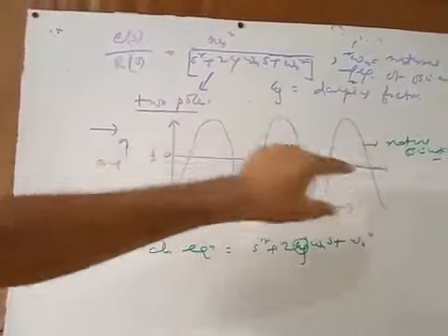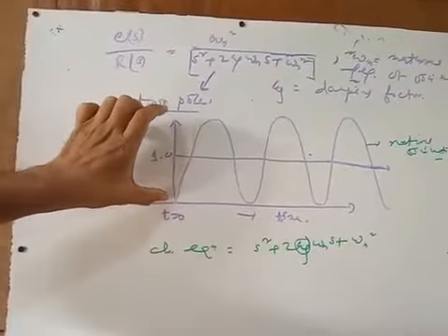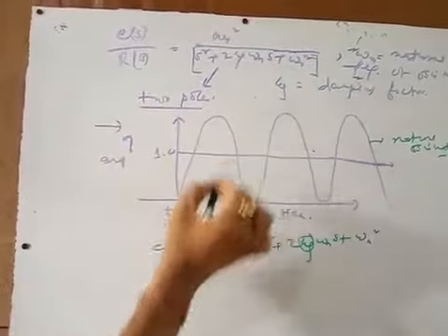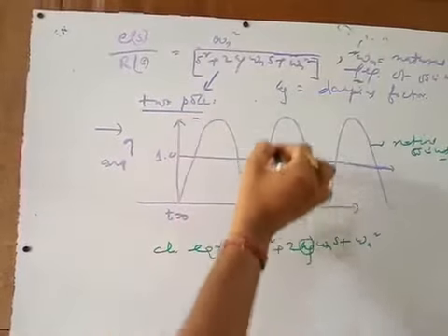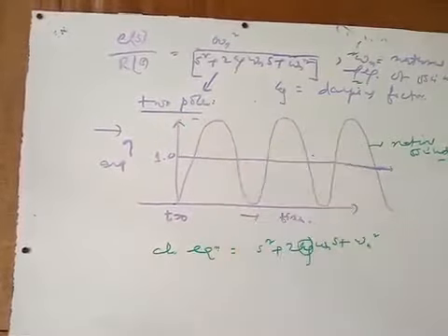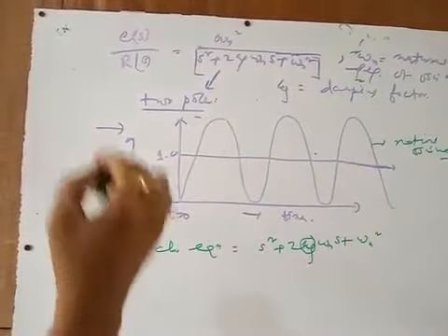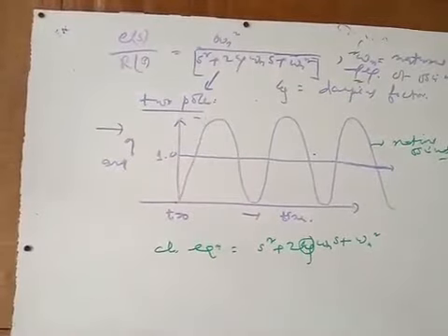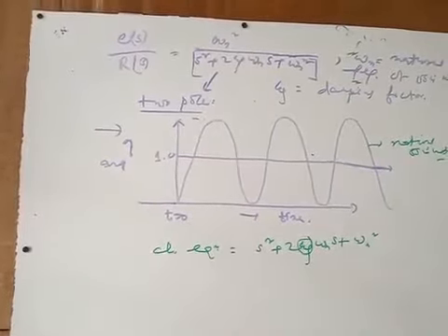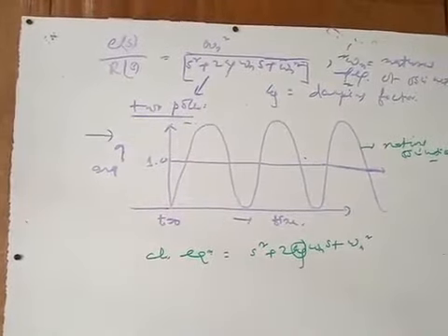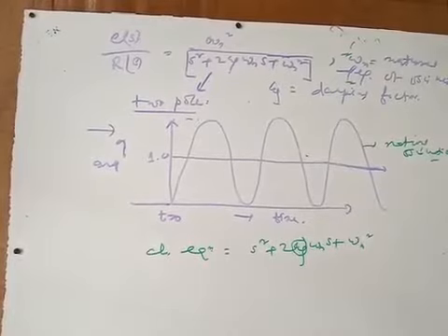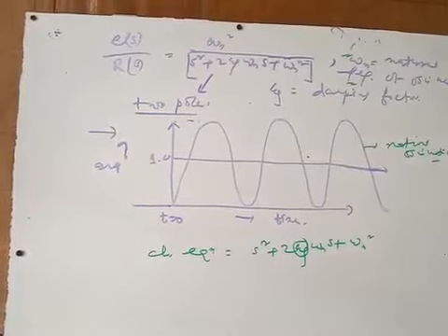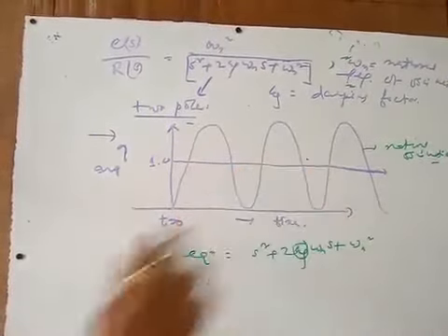You see, the oscillations have a fixed amplitude, lower part and upper part. This is oscillating in natural oscillation. Now when you apply certain kind of damping, say air damping, electromagnetic damping, water damping, whatever different kinds of damping are available, your aim is to reduce these oscillations, right?